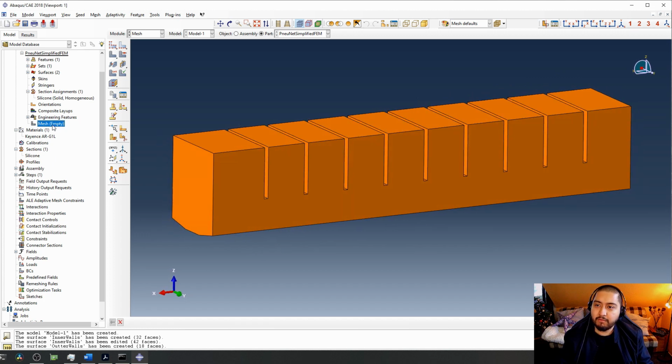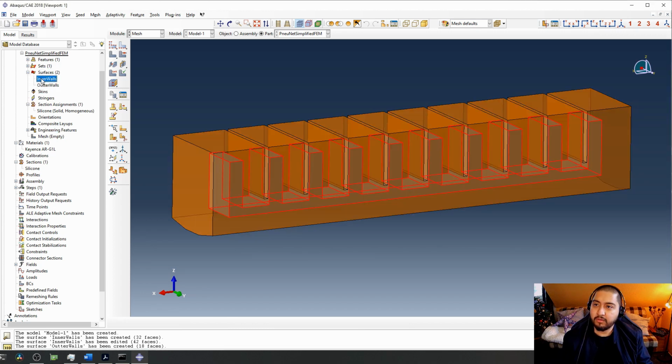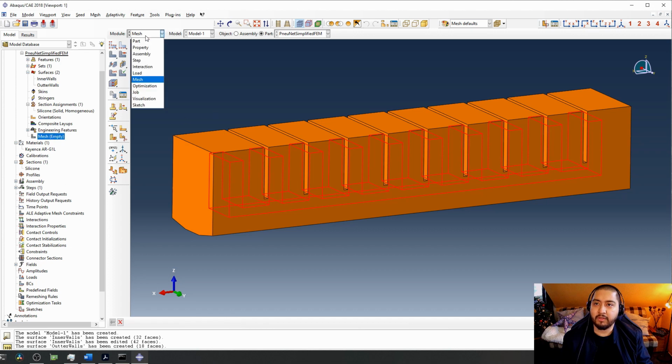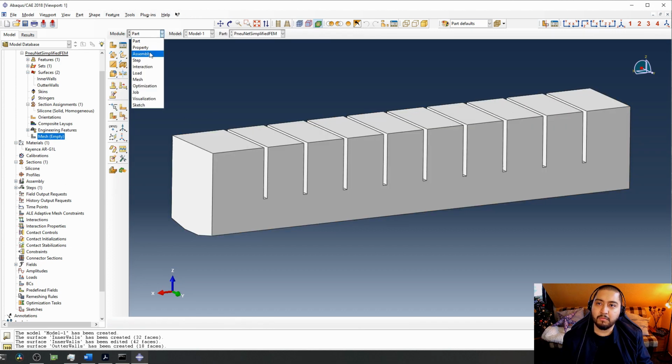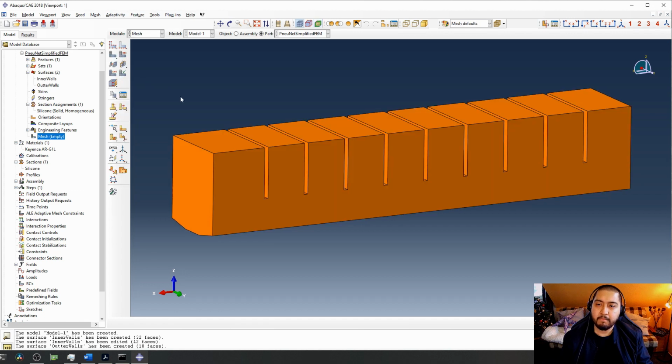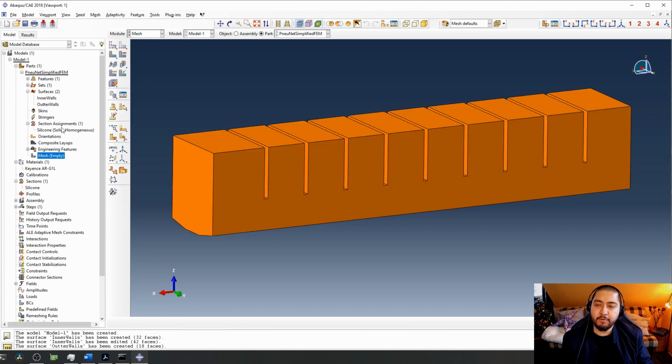So this is the mesh tab. Just double click. We were here. So let's click now on the mesh. Now we're here, or you can go here to mesh directly. I usually mesh the parts individually. You can also mesh in the assembly as instances. I don't do that. I always mesh individually. It worked for me, and I do it like that, and it works.